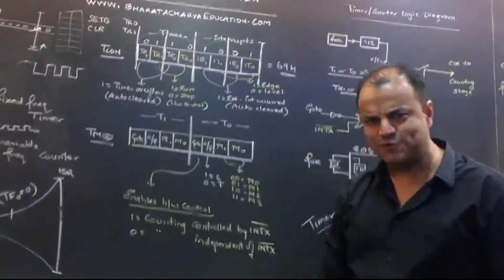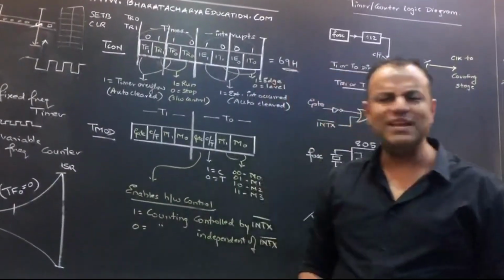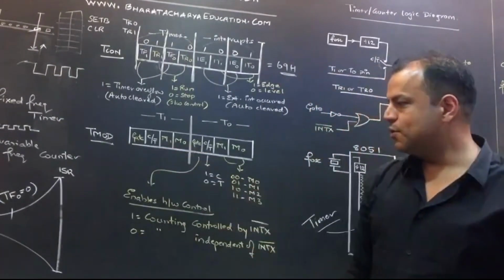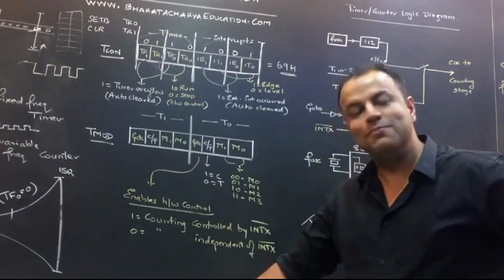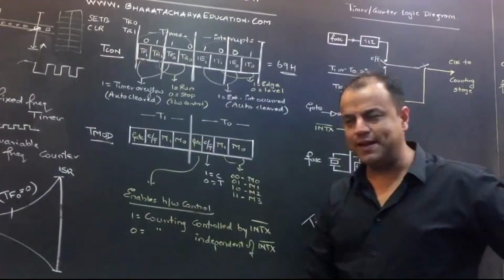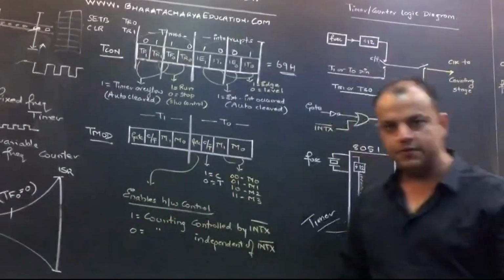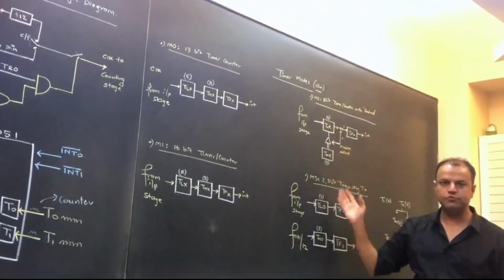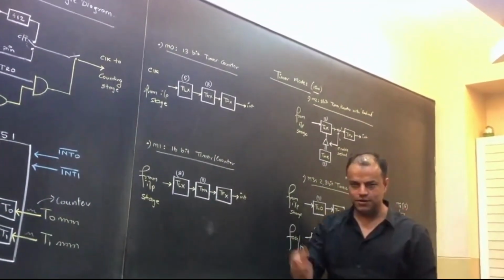And so is this, the next one, TMOD. They generally come together. Okay, but no such rule, but they generally come together. TMOD stands for timer modes. This is much simpler than TCON. Okay, it's very light. So in this register, we basically choose the modes of the timer. These are 4 modes. We'll be coming to this in a minute. Okay, look here.